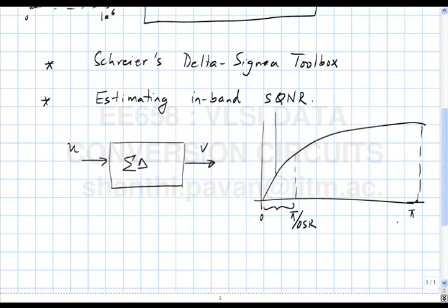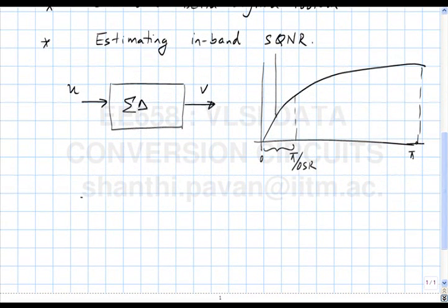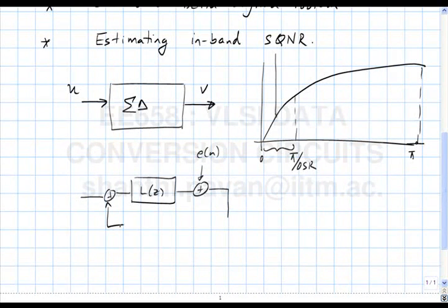All right. So, can you think of any difference between the output of a Nyquist rate converter and a delta sigma? The approximation you have for the delta sigma is that it is some loop filter and some uniformly distributed quantization noise. Can you tell me some difference between these two? More uniformity in the quantization noise. Pardon? There's more uniformity in the quantization noise in the Nyquist converter. What do you mean by uniformity? The noise is not shaped at all. Yes, okay.